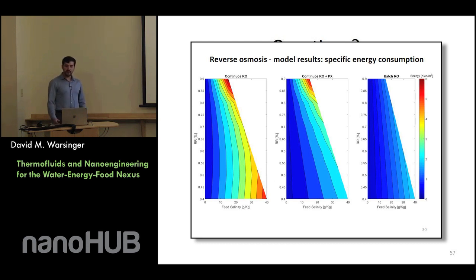Yeah, so the most competitive direct electrical method is electrodialysis. There you basically have desalination with a membrane. One membrane lets the positive ions pass, and one membrane lets the negative ions pass. And electric current can make them self-sort. At extremely low salinities, it's easier to make the ions move around than make the water move around.